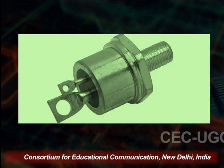It has 4 layers of alternating P and N type material, and it also has an additional control terminal which is called the gate. The presence of the gate allows the SCR to be triggered into conduction. The gate is required to trigger the SCR so that conduction can take place, and it is a unidirectional device that allows the current to flow only in one direction and opposes the flow in the opposite direction. And on the screen, this is the SCR that is used in most of the gadgets.